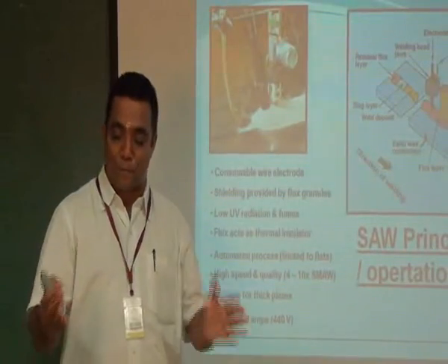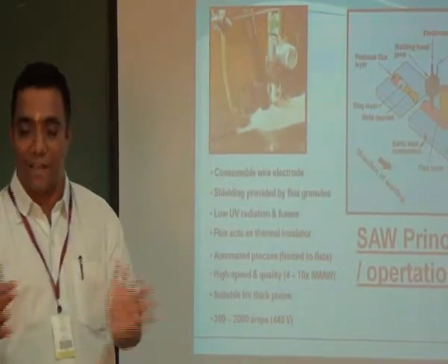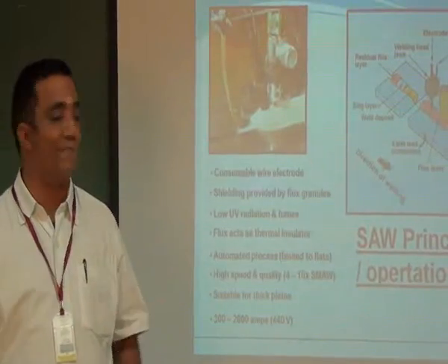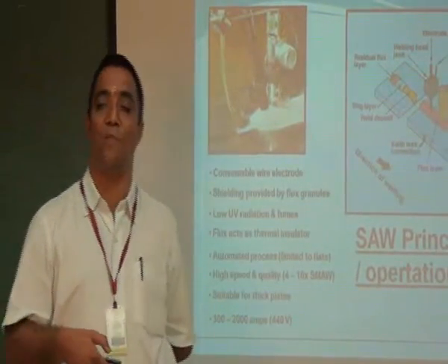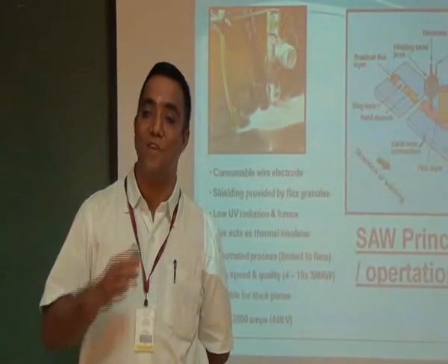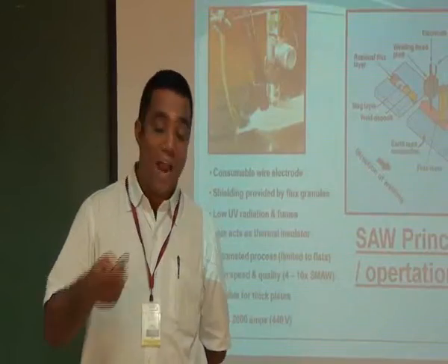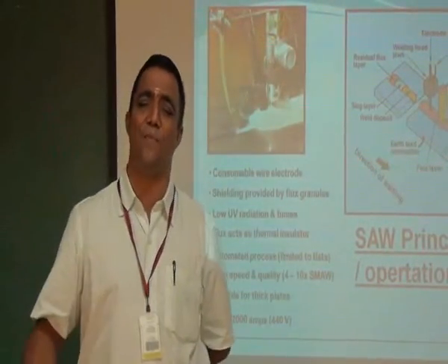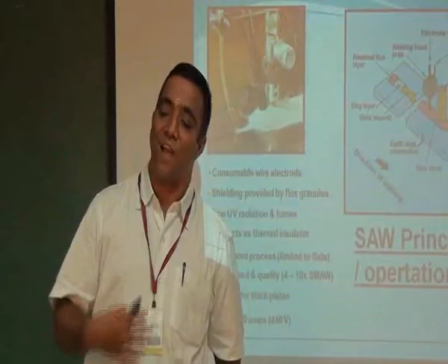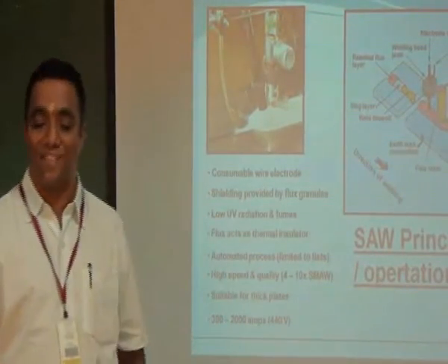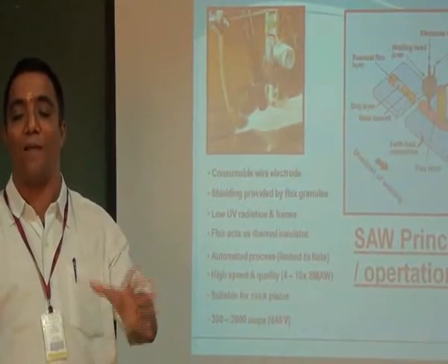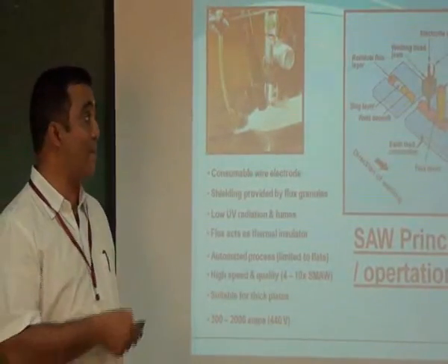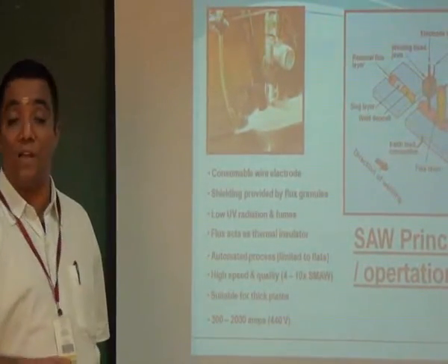Remember, the boiler pressure vessel casings, the 20 mm and 30 mm plates, are welded only by using the automated submerged arc welding process. This is widely used. This is the most widely used process for fabrication of thick-walled boiler pressure vessels. I am talking about the walls of the boiler pressure vessels being welded.